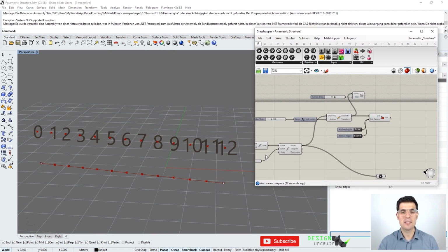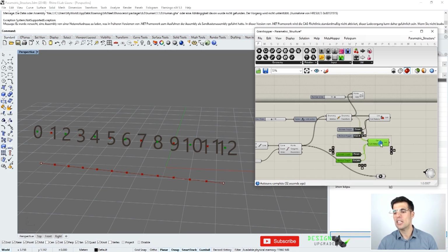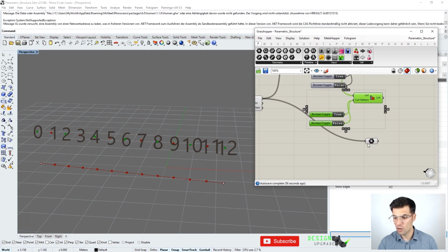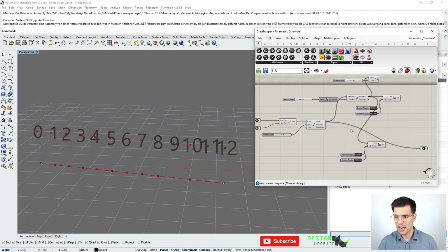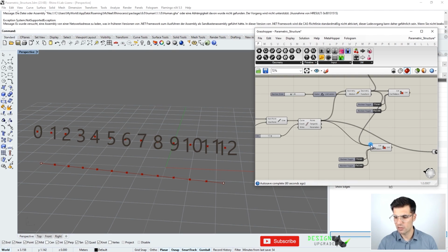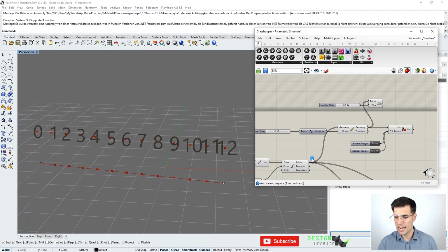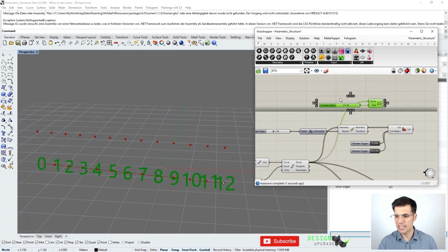And now let's move on to the lower chord here. And here we said that we want to remove every 2 points as well. So one way of doing that is to use the same cull component, and I've just copied it with Ctrl+C, Ctrl+V. And now let's connect the points of the lower chord, these ones here. Let's connect them to the point list as well.